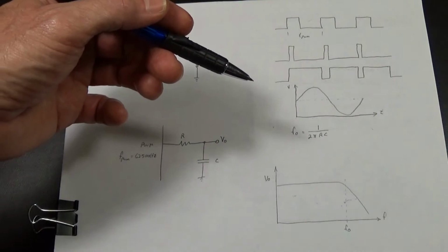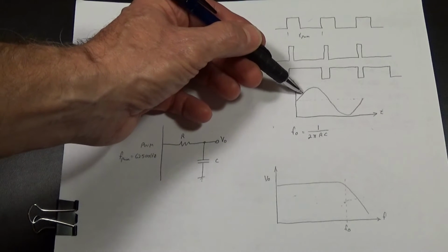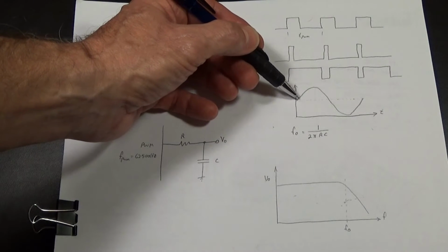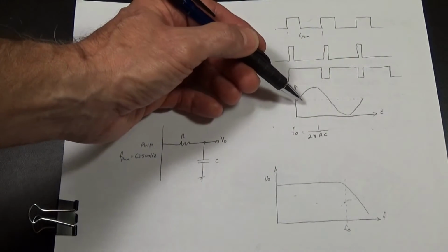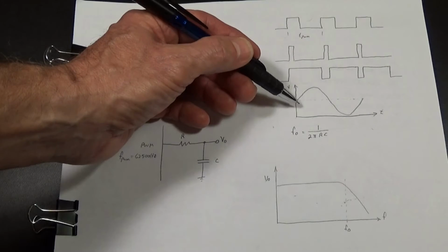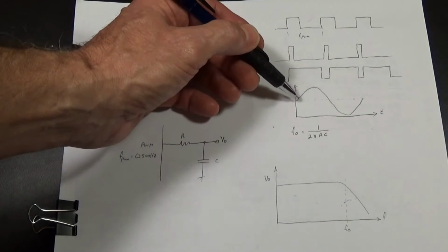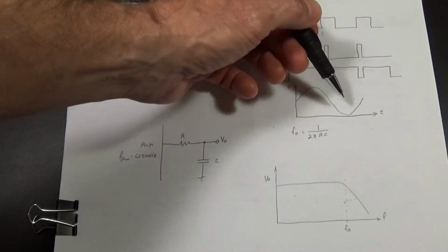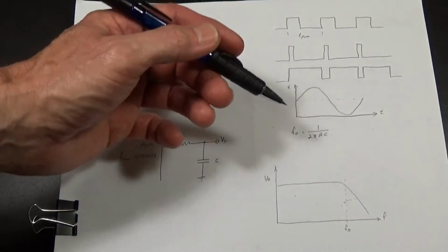Now if I wanted to create a higher frequency, I can start skipping some of these points and put only a few of them along the way. Instead of all 256 of them, I can just pick a few off, and the filter will smooth that out somewhat, and you'll get a relatively smooth sine wave, but it'll be much faster because we're only taking a few points along the cycle.